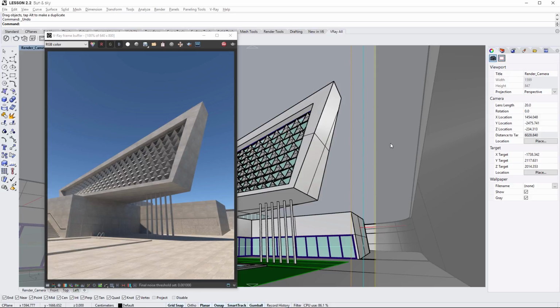In many exterior scenes, one of the most commonly used tools is the V-Ray Sun and Sky. It is a powerful system that enables you to achieve all sorts of natural lighting. One of the first things you'll often want to do when lighting an exterior is to set up the sun angle. By default, V-Ray is using the Rhino document sun, and its position can be controlled via Rhino's sun panel.